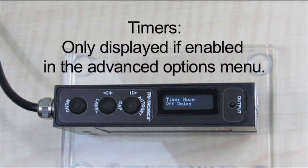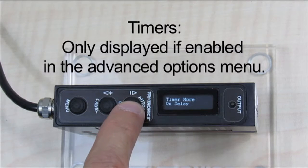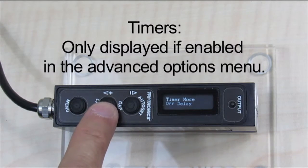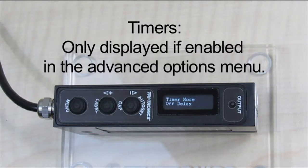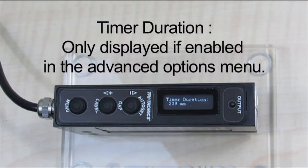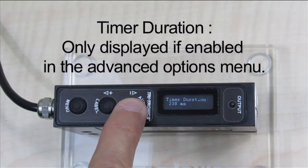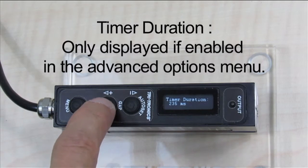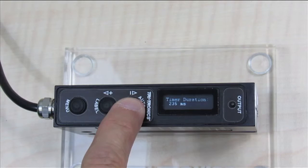The timer function allows you to choose one of 4 output timer modes: off delay, on delay, one shot, or debounce, by tapping either the plus or minus buttons to step through the 4 choices. Tap the menu button again to advance to the timer duration, where you can set the value of the output timer in milliseconds. The timer's range is from 1 millisecond to 9,999 milliseconds, or just under 10 seconds.